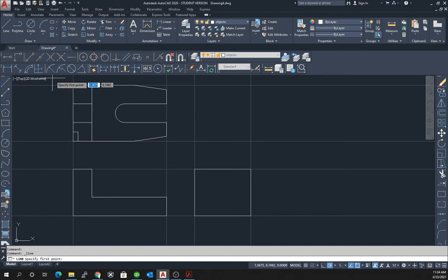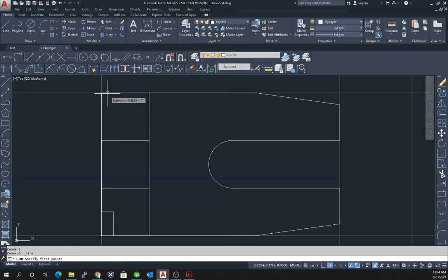And we do the same thing on the top. We'll blow this up a little bit. So we start here, haven't hit the mouse button, we hit 0.25, enter, 0.5, enter, and then here we don't have to hit 0.25, we can simply just bring it back to the intersection. Once we do that, we just need to trim out the pieces that don't belong. So we select those 4 segments, and then we delete, we delete, we delete, and we delete.